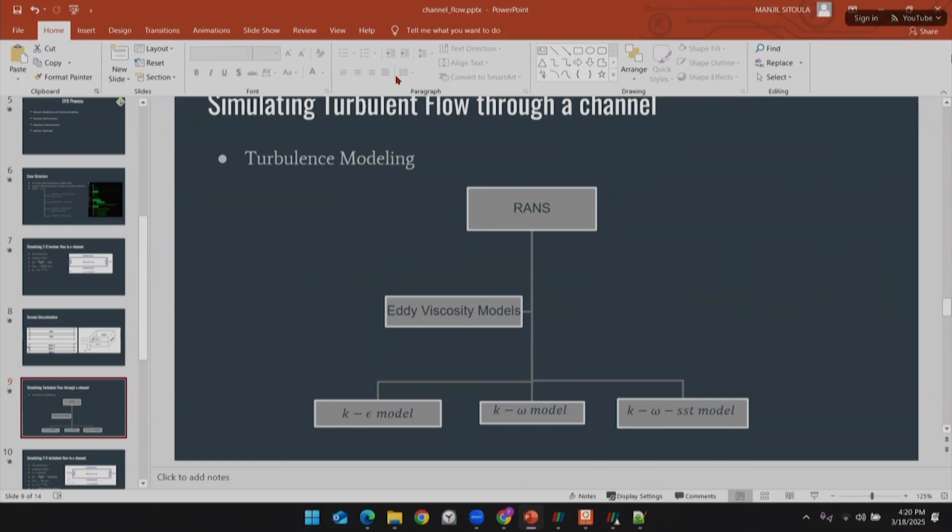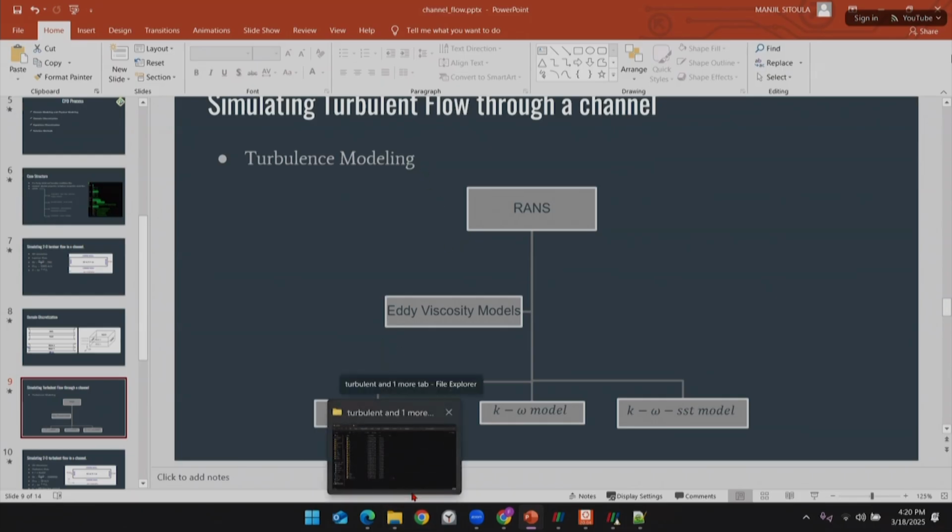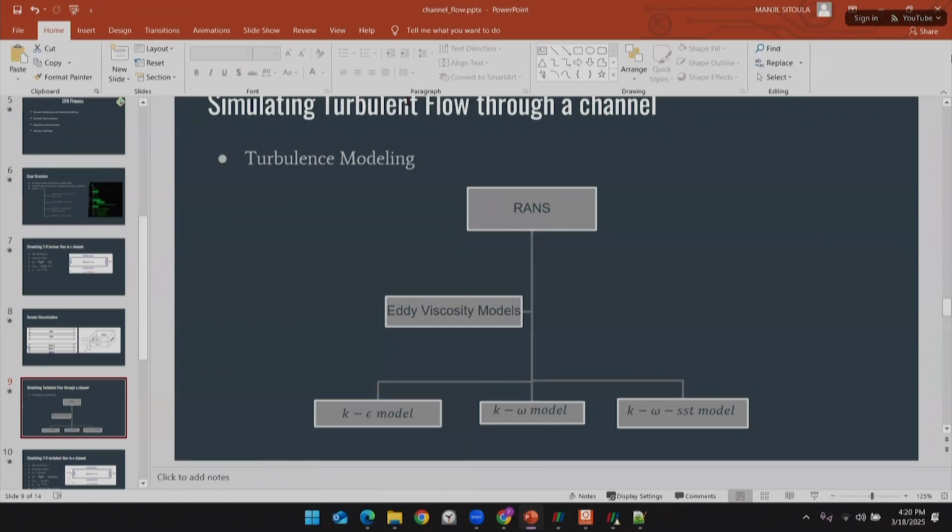Okay. You can use these solvers. There are various solvers in OpenFOAM. So you just go inside the src and see all the available solvers for your problem. The problem is related to multiphysics and electrokinetics, so you will have a different solver for these types of problems. Okay, so the constant files and zero files will be modified accordingly? Yeah, only the U folder, P folder, and boundary conditions will be modified. The file structure, the folder structure will be the same. Okay. Thank you, sir.